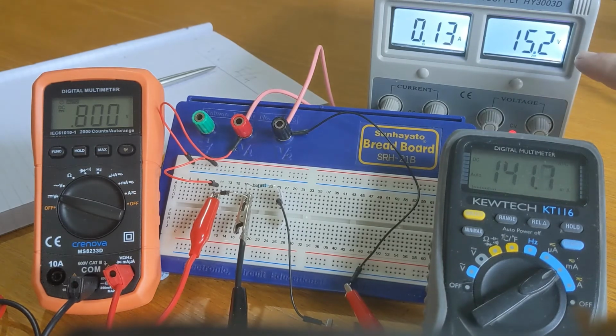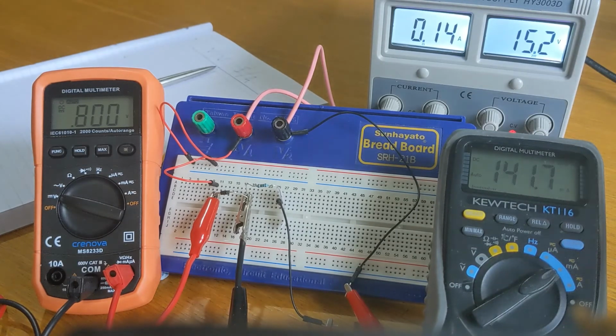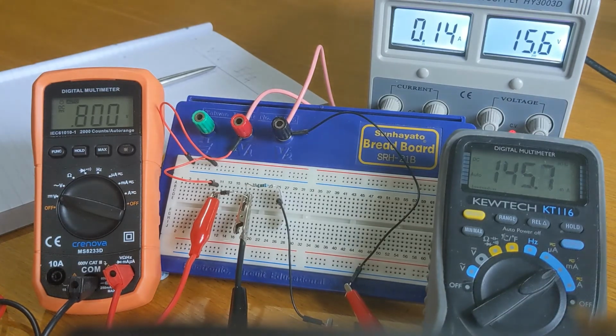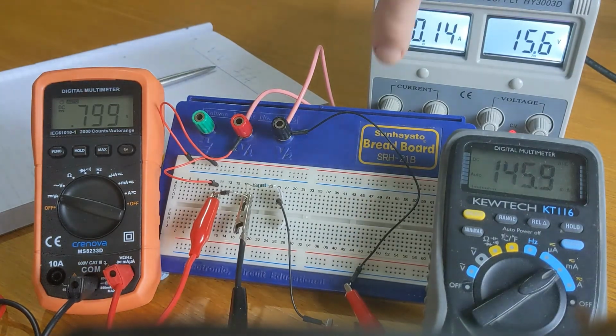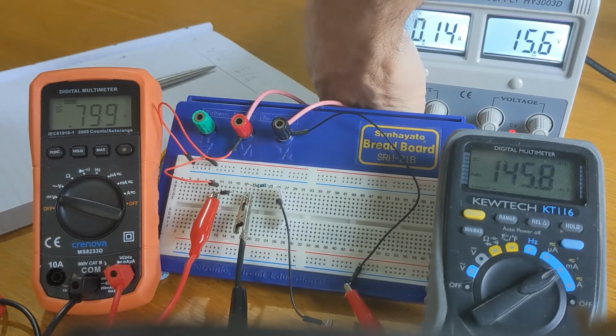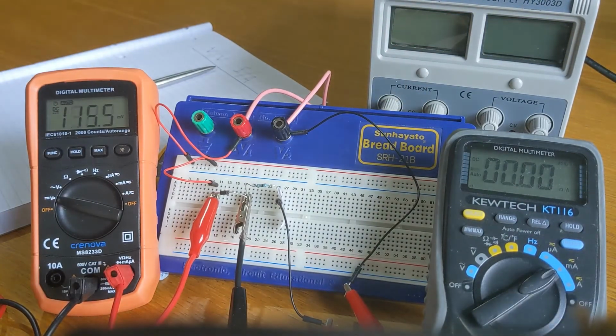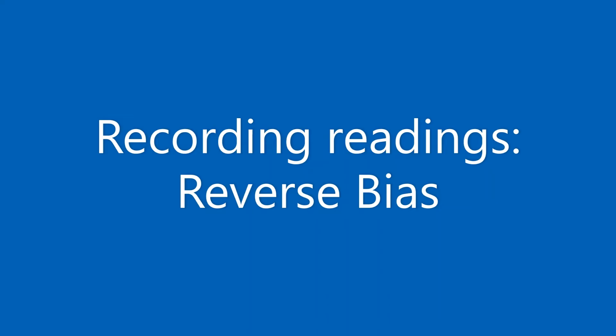We've now got 0.8 volts across the diode, over 15 volts from the power supply itself. And one thing that I can't record for you is that at this point you're beginning to get the smell of rather hot components. So time to turn things off and say that that is the end of our recordings for forward bias. So now let's go on to reverse bias.